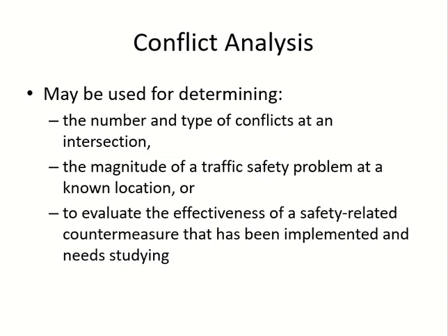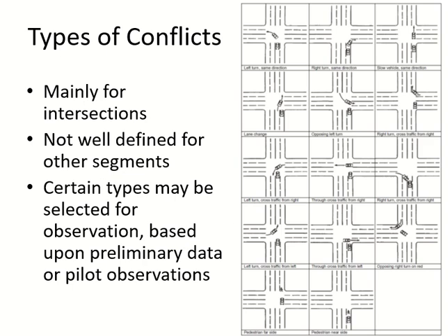You can do a conflict study to know. You don't have to wait for 6 months to see if the accidents are happening or not. You can do a conflict study right after you have installed the speed hump. Next day you can do a conflict study. In 1 hour you would know whether the problem is solved or not. So this is a very easy and efficient method.